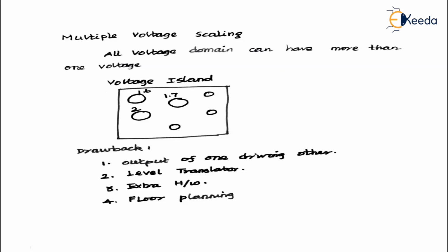So for that, what I must do is a level translation. When I want to use a level translator, it is going to be hardware circuitry, and because of these voltage islands, the various circuitry and the interconnections between all the circuitry, the floor planning becomes a tedious process.